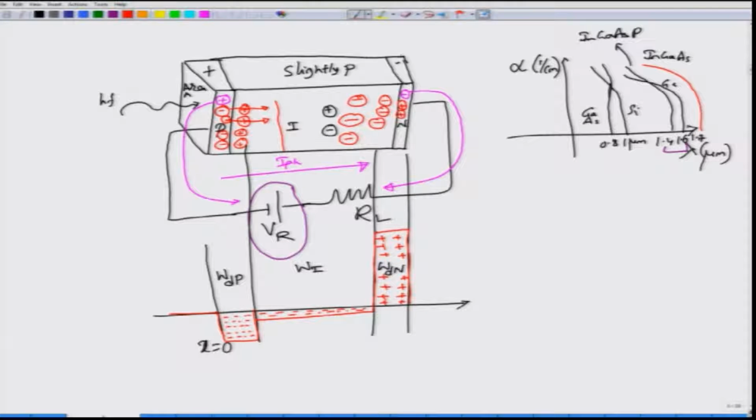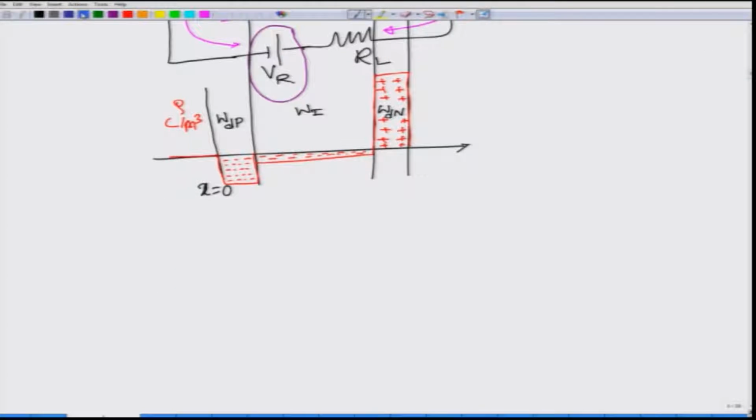Okay. So, this is essentially the charge density rho, measured in coulomb per meter, you can say. This is the charge density as a function of the cross section, or the length along the photodetector. Now, while this is charge density, how about the electric field? How can you find the electric field from the charge density? Well, you can use Poisson's and Laplace's equations.